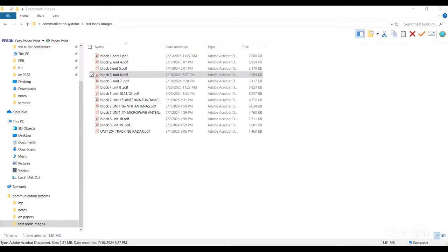Again, in this, we have two types. The first one is the two-hole directional coupler, and another one is the scattering matrix of the directional coupler. First, we will see the two-hole directional coupler. Just observe the diagram. Here also we have two waveguides, primary and secondary, with a slit in the middle.